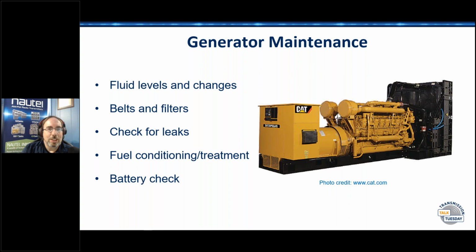One of the things I didn't mention, and I had it happen to my own generator outside the house a couple of months ago, was I went to fire it up and it wouldn't start. Turned out that the rubber hose going from the air cleaner to the carburetor had just about totally disintegrated. Now, being highly creative and somewhat frugal and not having the proper part at hand, I discovered that if I wrapped the hose with duct tape, it held together nicely. I wouldn't necessarily recommend that for a radio station that's paying your bills.